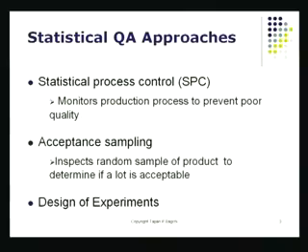So let's get into the lecture and let's try to understand what we mean by statistical process control, which is also called SPC. What is SPC? It actually monitors the production process online. As the widgets or as the output is coming out, you measure some certain characteristics of interest of the output. Then you collect some data, which would be a sample taken out of the output, and then you look at the statistic, which could be something like X bar or P or R or something like that, and you trace basically the variation of that statistic.